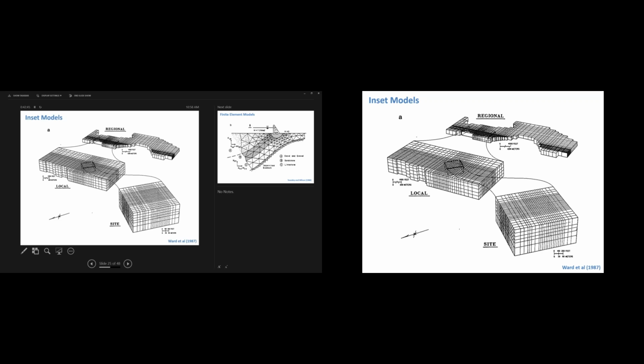You can take a small portion of it, and when you telescope, it sets constant heads or whatever kind of condition around there. Since you're not adding a pumping stress or changing a water level, you're just doing the mass transport, so the flow won't change. And so you can get away with doing just a smaller subset.